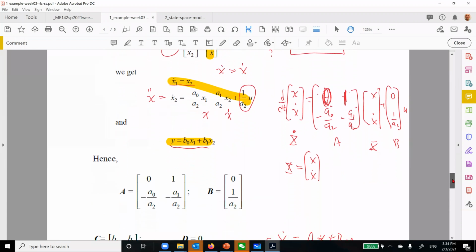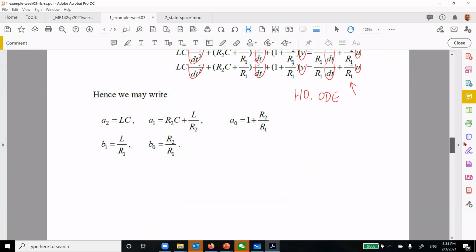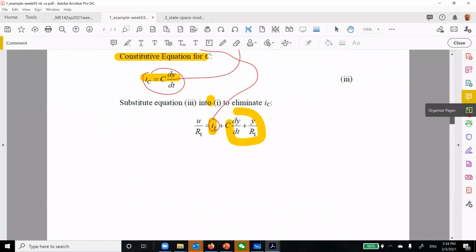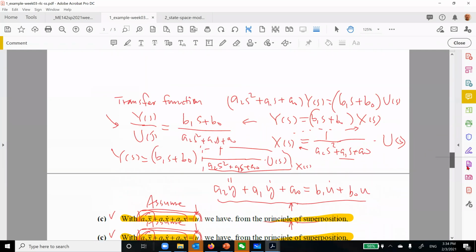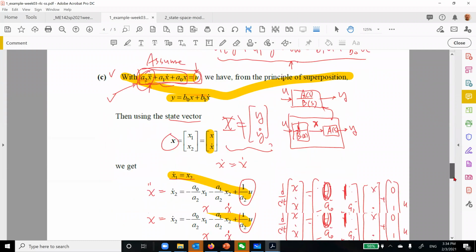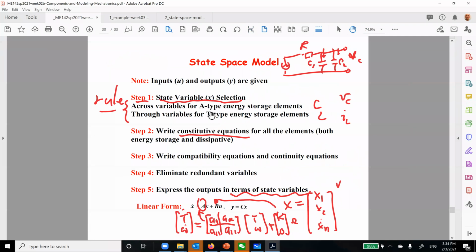I know this is a little bit off the way, but indeed, this is the right way to go. We haven't still answered the question why we cannot use y and y dot as a state vector. We need to answer this question. Again, as I said, a state variable cannot suddenly change, because if you suddenly change, your d/dt will be infinite. It's illegal, anti-physics.